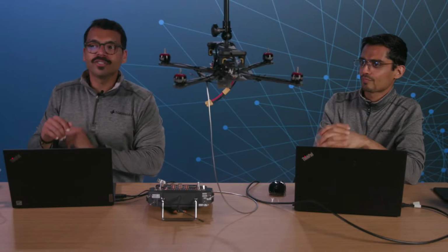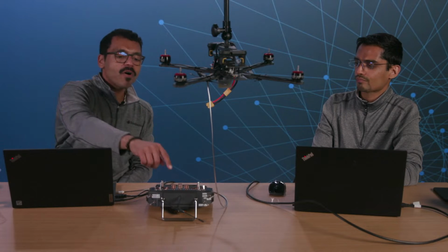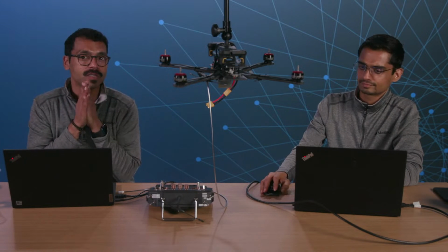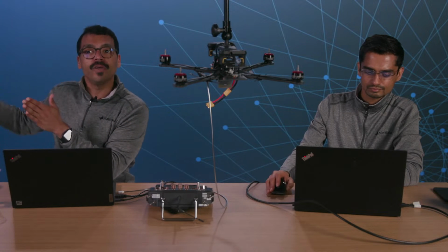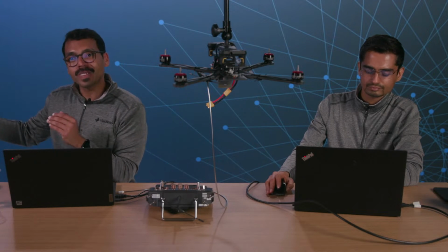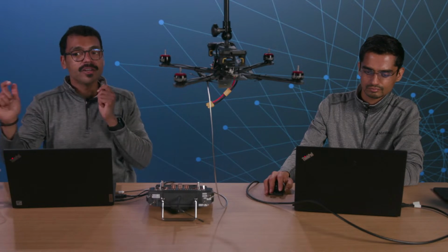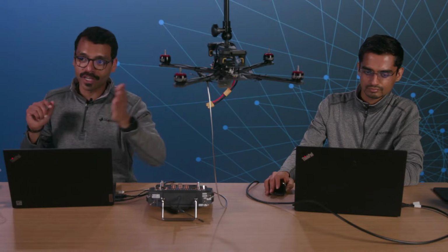actually happening. So you can see in the Data Inspector, well, once I actually unplug this, you can't, but in Monitor and Tune, what you want to do is utilize your Data Inspector, make sure that the signals you expect when you are yawing, maybe let's call this minus and this plus. When you're in minus, you have 2 of the counterclockwise ones spinning to turn you back, and when you're in plus, you have the 2 clockwise ones spinning to bring you back.